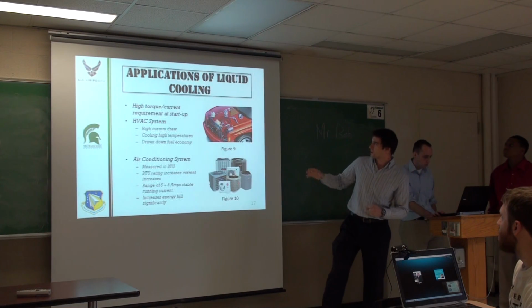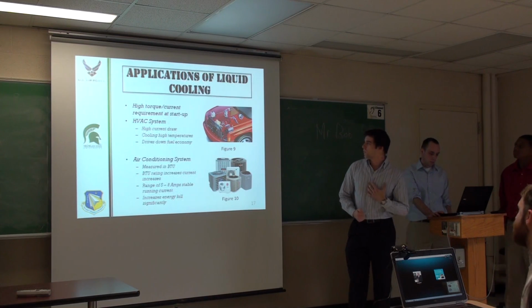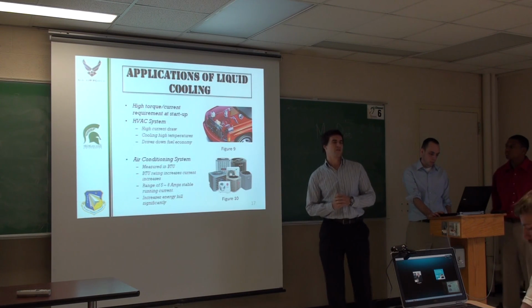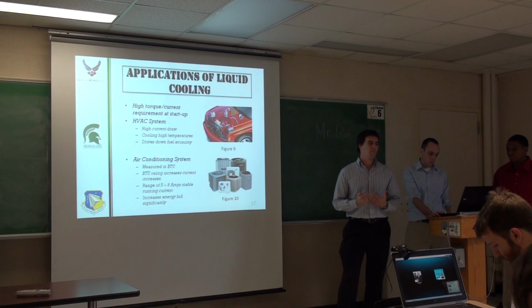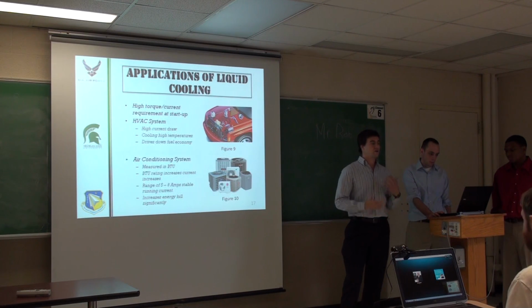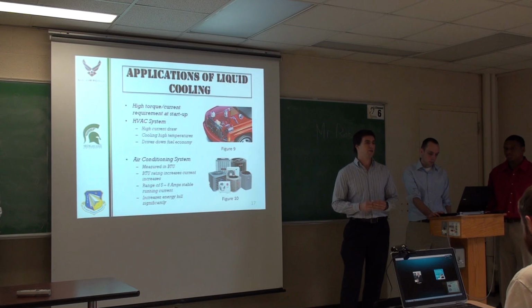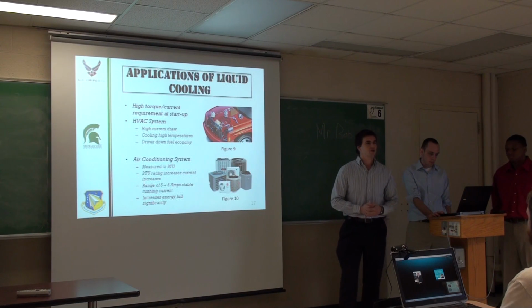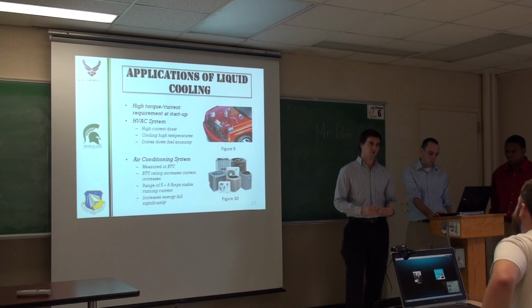So I want to quickly summarize some of the applications of it, which you all are aware of. But one thing to notice about a compressor in general is that compressors require a very high startup surge current. For everyone who's taken 320, which should be everybody in here, we know that torque is required for an engine to start, or a motor. And torque directly correlates to current. So generally for every compressor, 3 times the running current is required to start the motor.